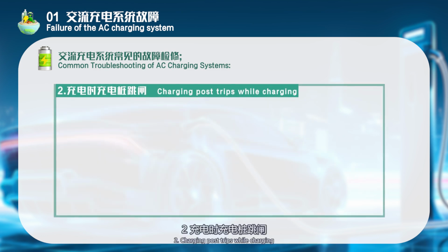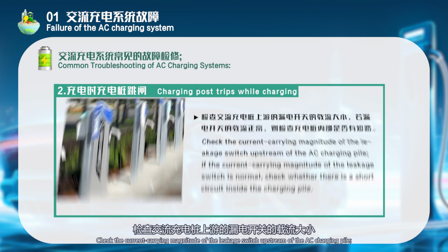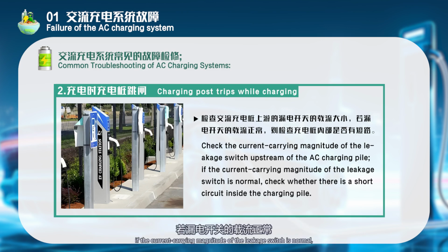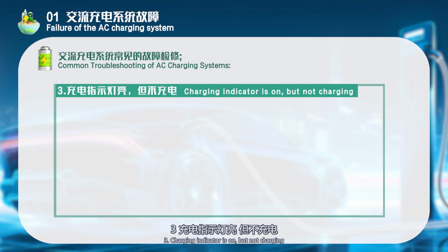2. Charging post trips while charging. Check the current carrying magnitude of the leakage switch upstream of the AC charging pile. If the current carrying magnitude of the leakage switch is normal, check whether there is a short circuit inside the charging pile.